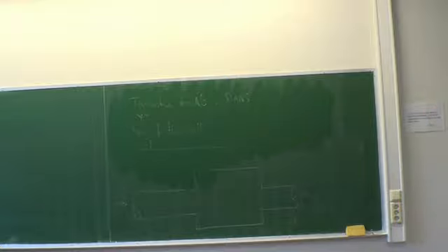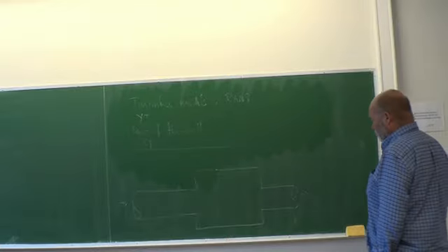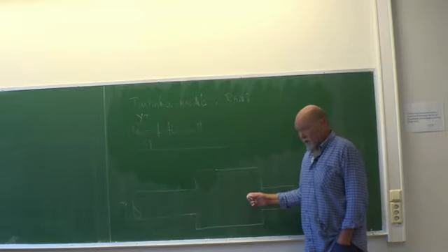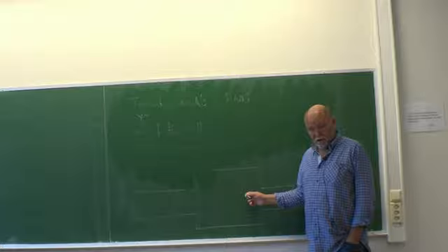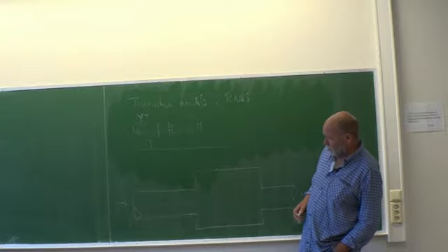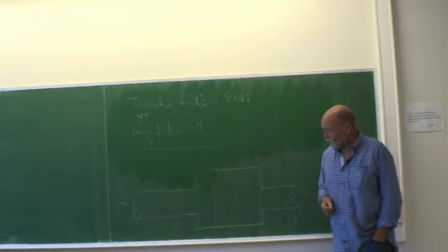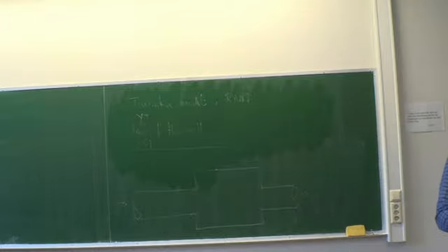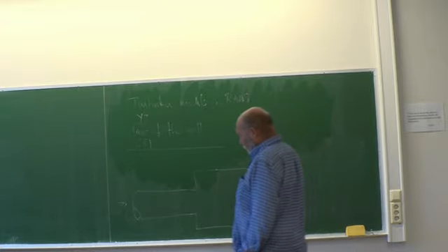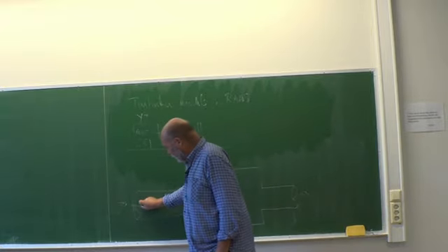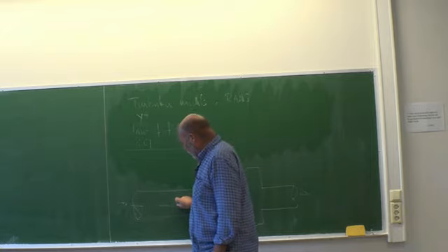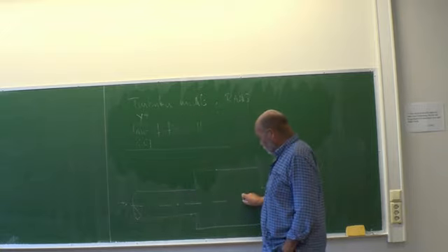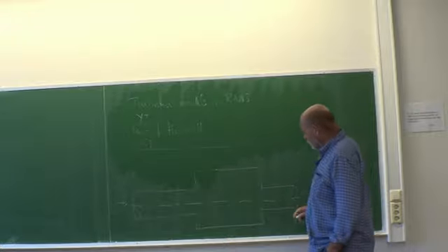This is your job. Now, to do this one in full 3D, that's quite heavy. And typically here you would use cylindrical coordinate systems, which is rather messy. But we don't need it. This problem is axis symmetric. So we put in, not a symmetry plane, but a symmetry line along the center, like that.